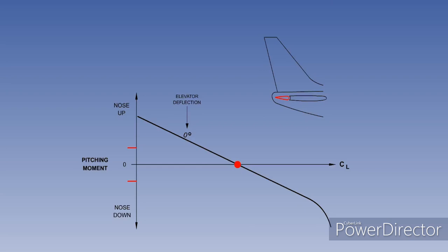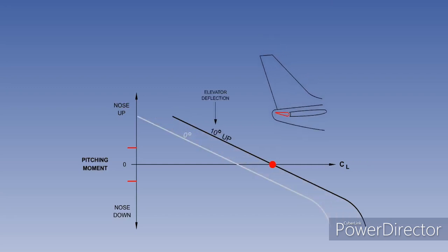The illustration shows a certain amount of static longitudinal stability, with the elevator at neutral. The aircraft is maintaining level flight by increasing the angle of attack as the indicated airspeed is decreased, until once again it is in equilibrium at a lower airspeed. To hold this angle of attack at a lower airspeed, the elevator must remain displaced at a position 10 degrees up from neutral. A momentary increase in angle of attack generates the same stabilizing nose-down pitching moment.